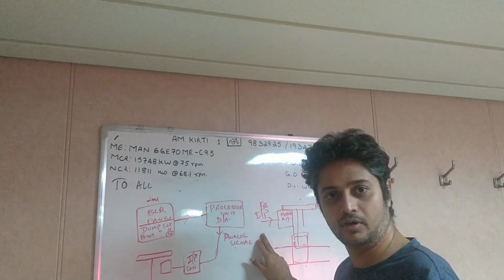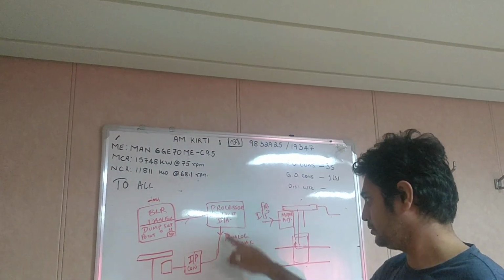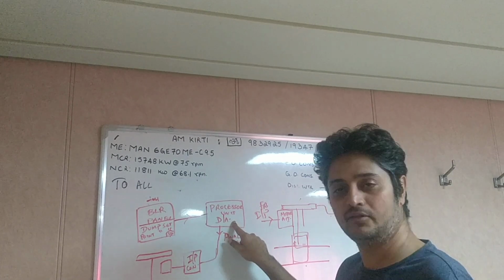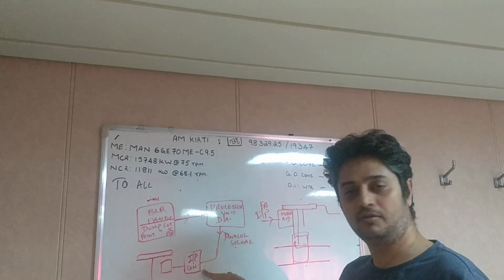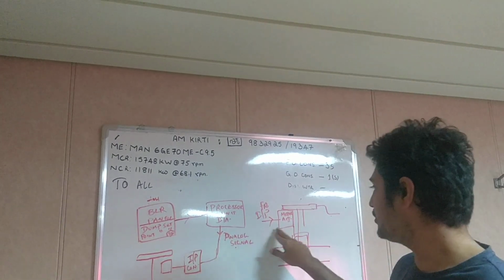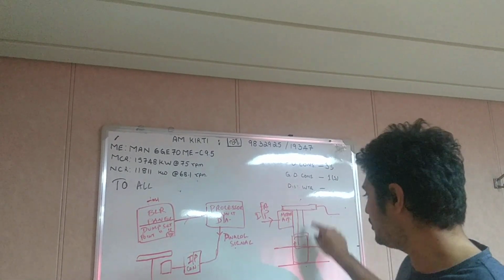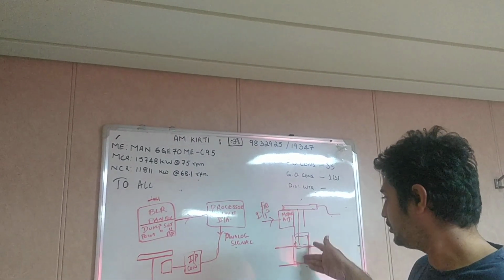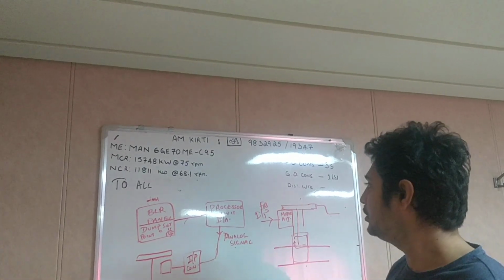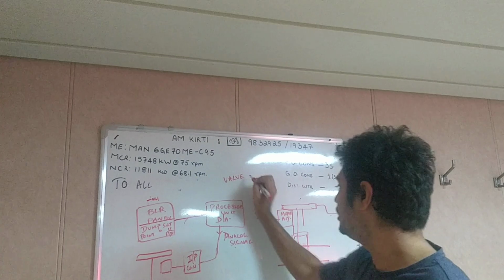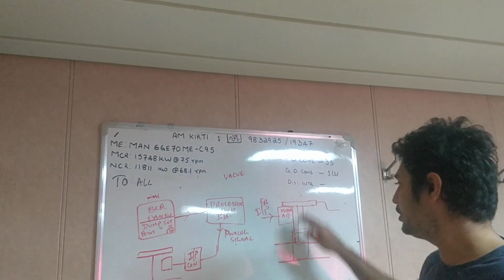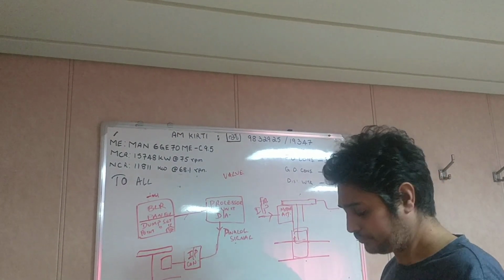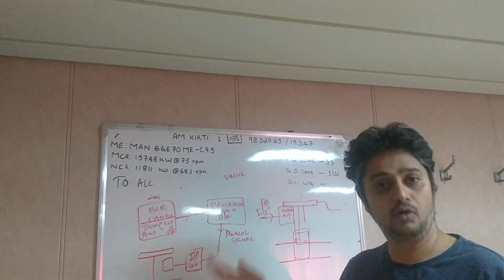I hope now you got a brief idea what is happening. So from the processor unit, your analog current signal will be converted into the corresponding pneumatic signal. This pneumatic signal goes to the motor actuator, which in turn operates the pneumatic valve of the controller. Okay, this is a valve. If you see the drawing, the valve control system, you will know the construction of this valve and how it operates as per the pneumatic pressure given: when to open, how much to open, how much to close.